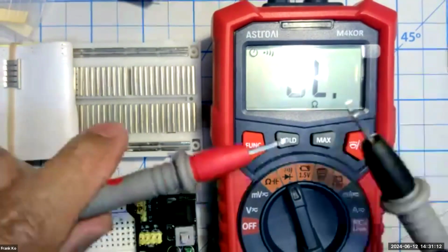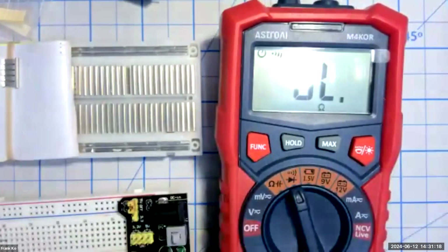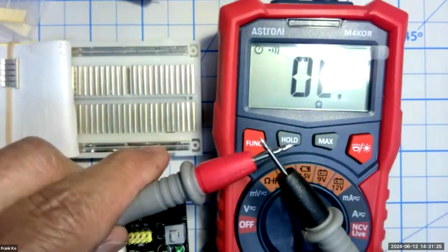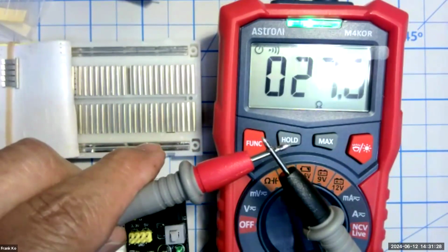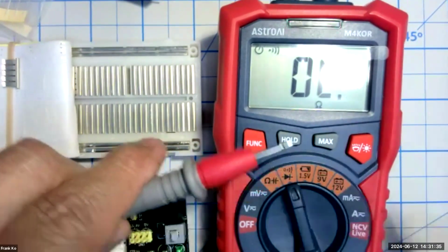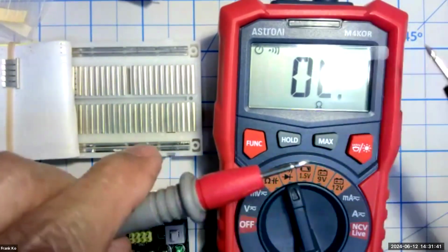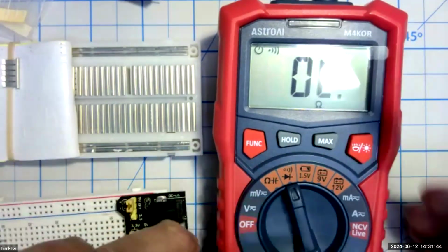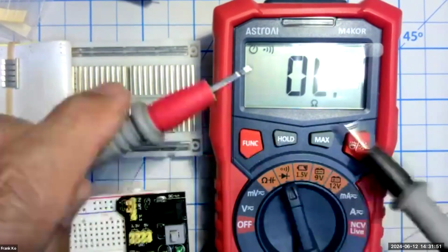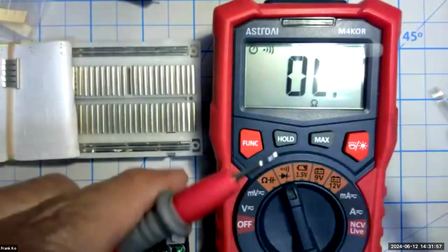And when I go to touch these two together, listen carefully, and the display will change also. Let me see how I can do this. Okay, ready, set. Hear the nice beep? That shows my test leads have continuity and they're working nicely. This particular nifty multimeter also happens to have a colored bar here that'll light up in addition to the sound. And the display is measuring how many ohms there are, how much resistance is in the wire itself.